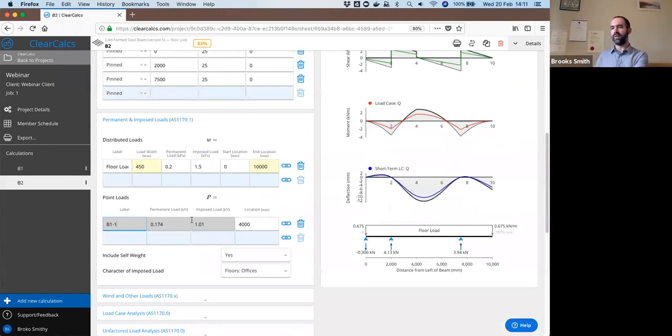We don't currently let you, within our calculations, set what the specific locations are of the bracing. We're just taking the maximum worst case values. But typically, if you are connecting a beam there, you are going to have lateral bracing. All right.